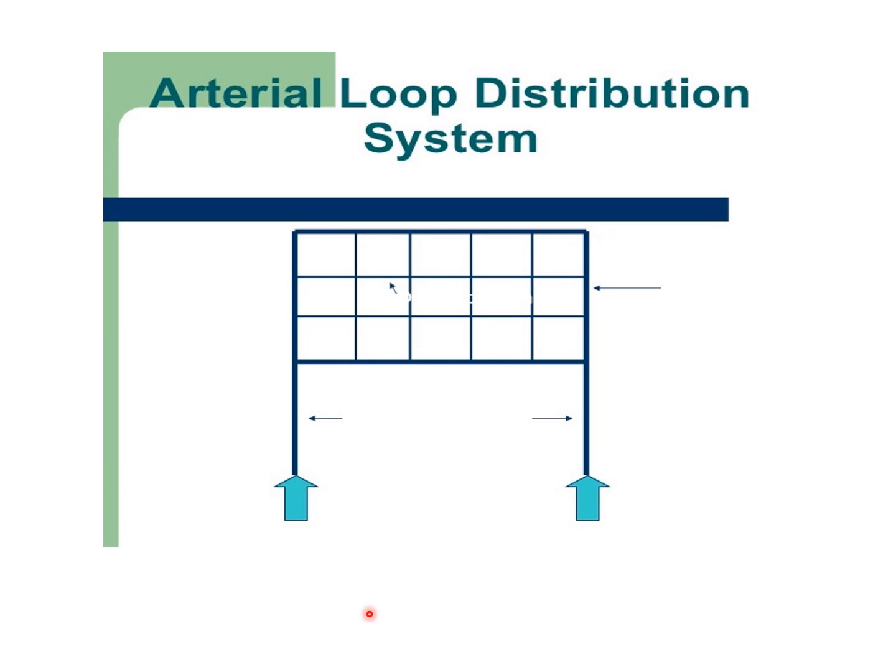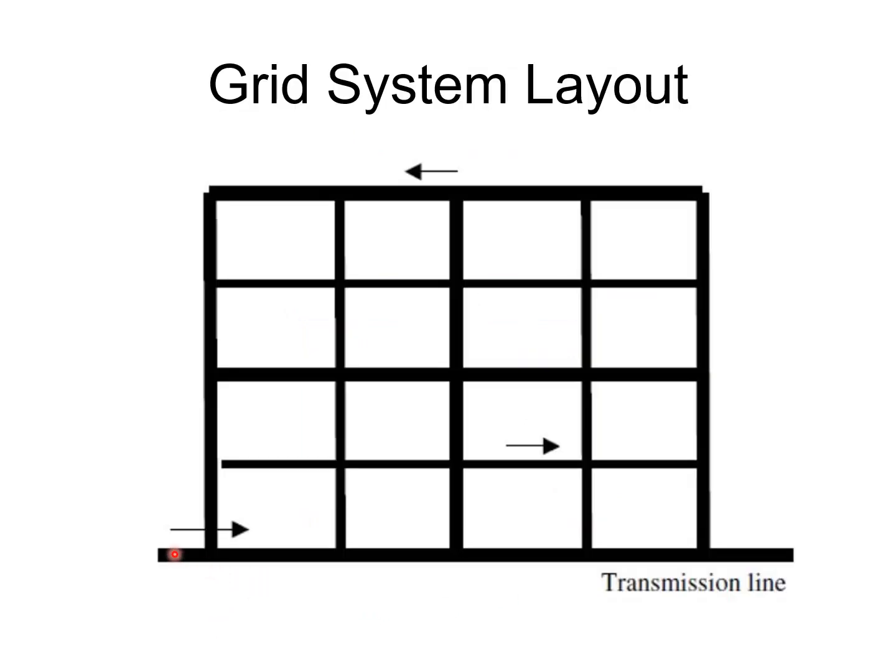You will see something similar in a grid pattern, such as this one. You can see you've got a large transmission main connected to smaller distribution mains. This one's considered a grid system just with how the grid pattern is set up. The city of Escondido is a good example of this. A lot of their system or their city is designed in a grid-like pattern, which is good for water quality.